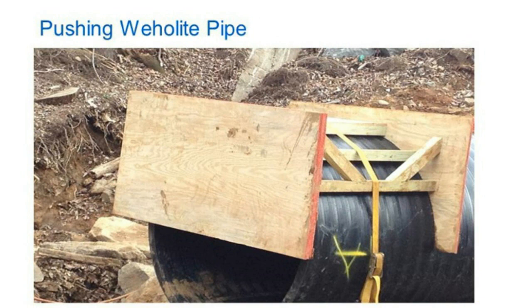So probably a more common push plate that you might see in the field, much easier, less expensive, easier to construct in the field, is by just simply using some plywood and some framing material and be able to construct a plate box to set over top of the pipe here. And this works just as well and at much less cost and much easier for the contractor to construct in the field if he gets to the point where he's going to be required to use something to apply a greater pressure than he anticipated.